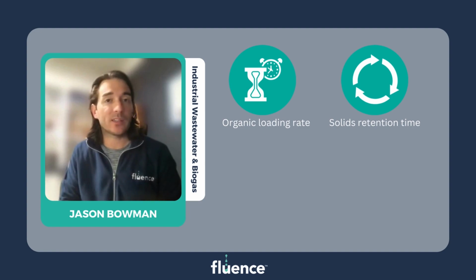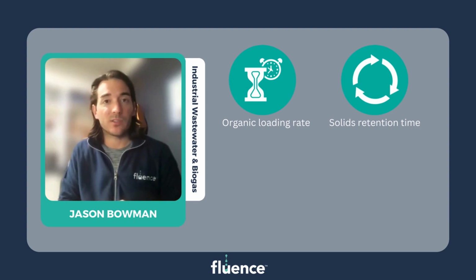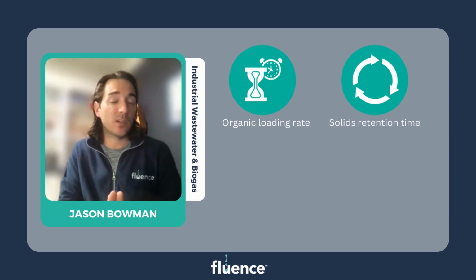What you'll find in practice in an operation is that some digesters, say plug flow, essentially what comes in is what goes out. Other digesters have a more sophisticated control strategy where these bacterial solids can be collected and recirculated. In this manner, you can maintain the time that the bacteria have to do the work, and this can be decoupled from the hydraulic retention time. And this becomes really critical when we talk about different digester styles.